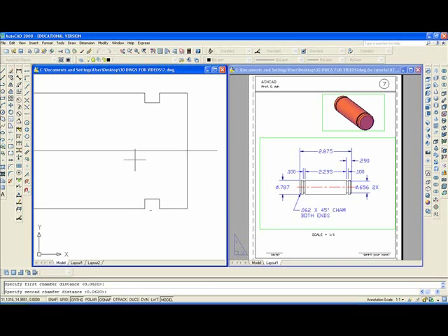The second distance is 0.062, I'll accept that. Now all I got to do is select the two lines, like that, and connect those lines with this straight line here. Repeat the command, here, here, hit the enter key twice, here, here.